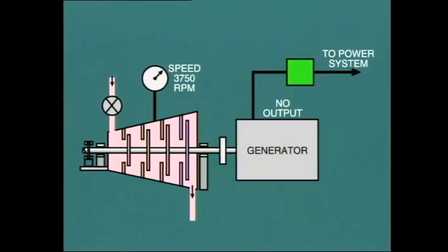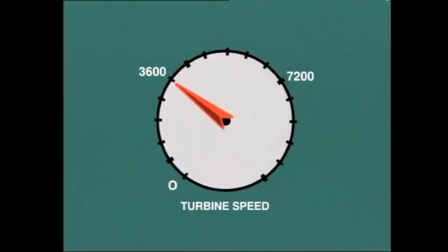Under normal circumstances, the governor should be able to close the turbine control valves sufficiently to bring the speed close to normal within a few seconds. However, imagine what would happen if the governor failed to act properly, or the power piston seized, or some other defect prevented movement of the control valves. In this case, steam flow to the turbine would continue, with the result that the speed would rapidly rise to 2 or 3 times normal.